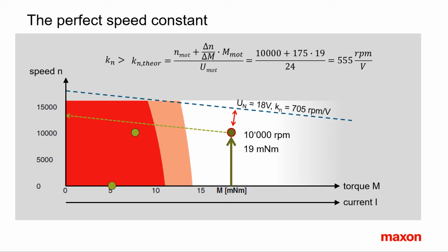A remark just to make things clear. Do not refer to the nominal voltage for the winding selection. The nominal voltage is just the reference voltage for specifying motors. It's irrelevant for the motor selection.